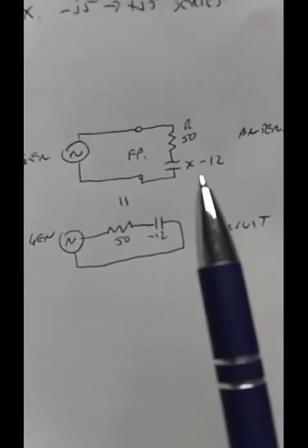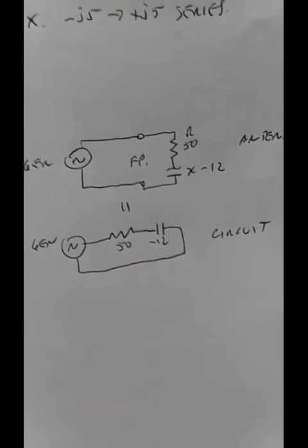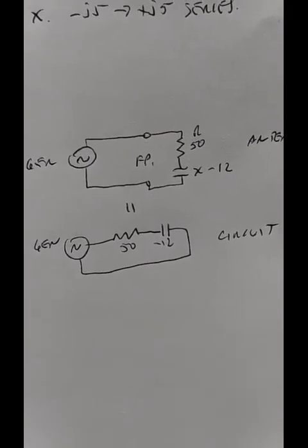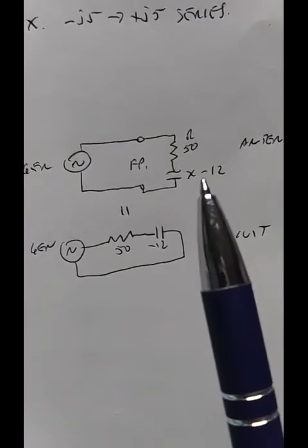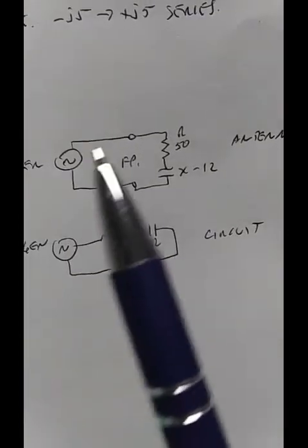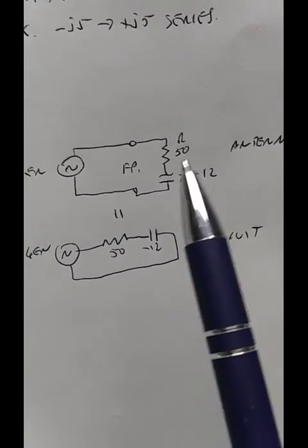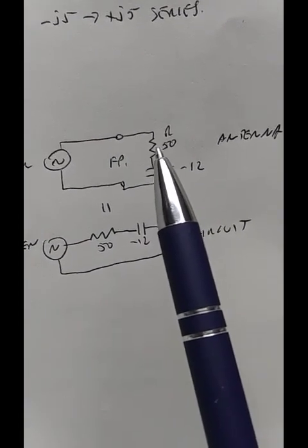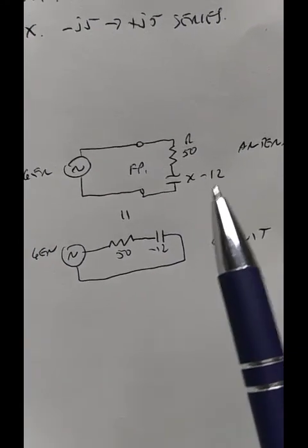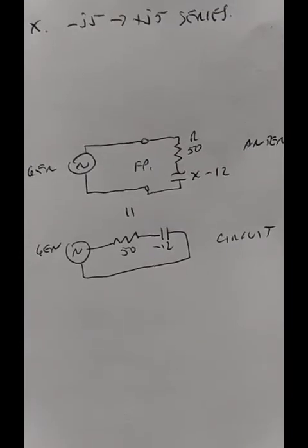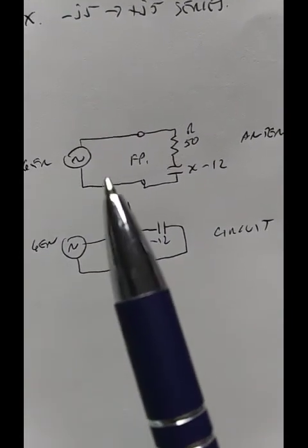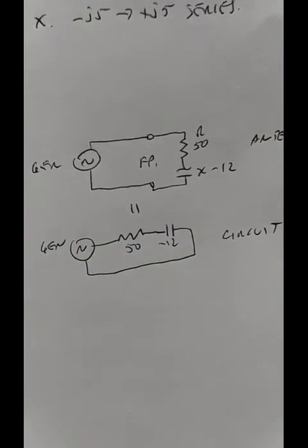The condition of the antenna has actually been made worse by tuning it, in a sense, because now more energy is being delivered to the antenna for more to be lost there. Yes, there'll be some more emitted through the antenna transfer function into this resistance, into emission into free space. It also increases the losses; we shoot ourselves in the foot. Yes, the transmission line's happier. Yes, the SWR meter thinks it's happy. The transmitter looks happy. All is not well.